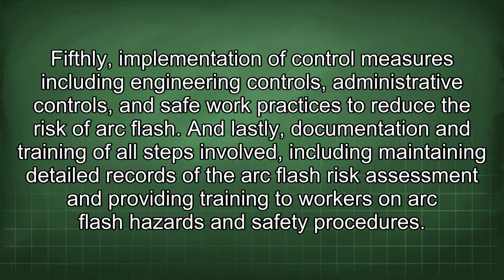Fifthly, implementation of control measures including engineering controls, administrative controls, and safe work practices to reduce the risk of arc flash. And lastly, documentation and training of all steps involved, including maintaining detailed records of the arc flash risk assessment and providing training to workers on arc flash hazards and safety procedures.